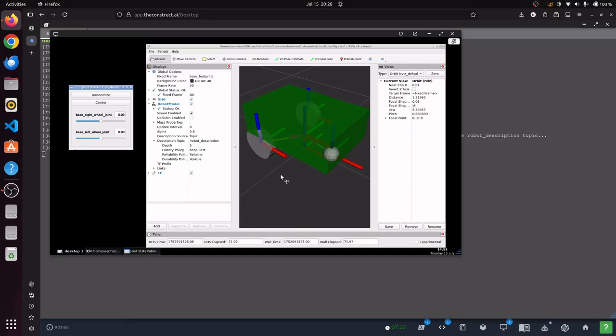And the other thing it needs is the joint states publisher. So you see this small window, this is the joint states publisher. What this does is it gives the states of the joints. Basically, suppose it's a revolute joint, revolute means it supports rotation in one direction and no other movement in other axes, no other rotations and no translation at all. So the software needs to get these states of joints from you so that it can calculate the TFs.